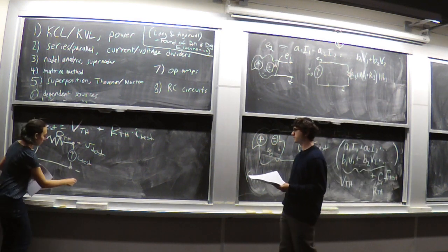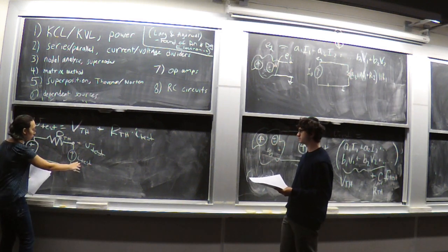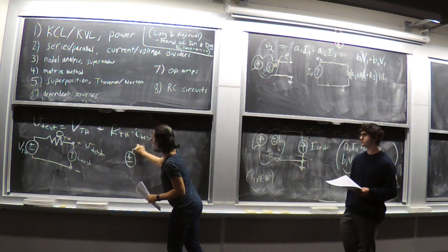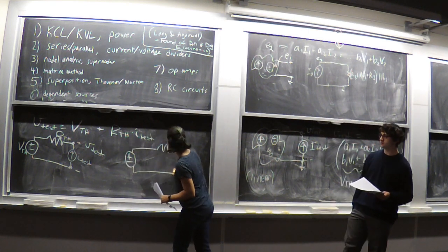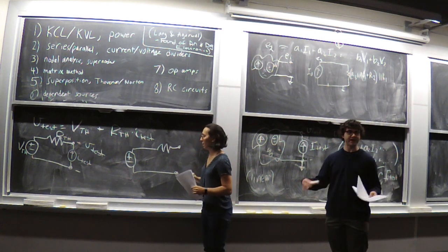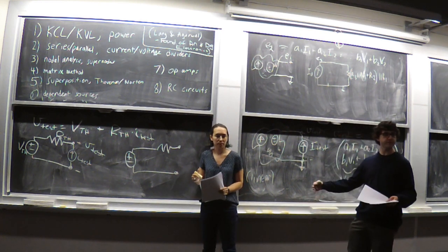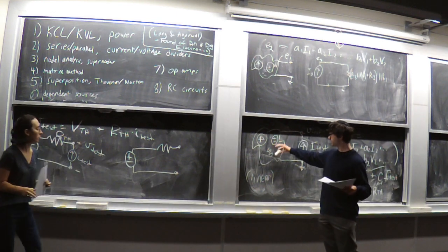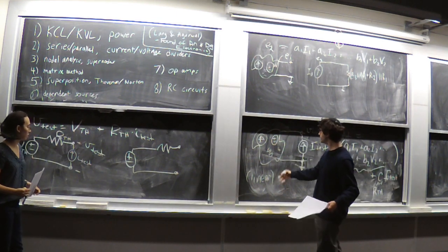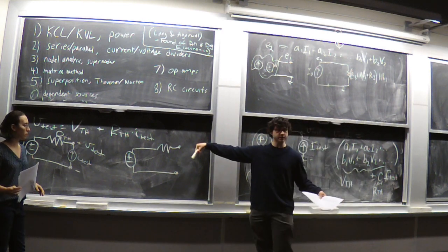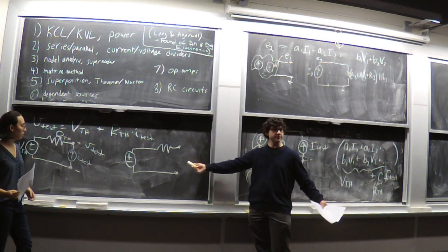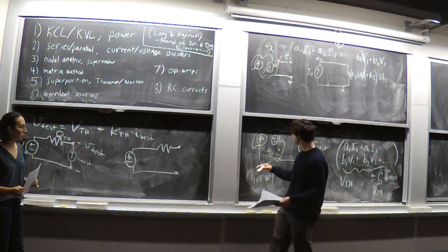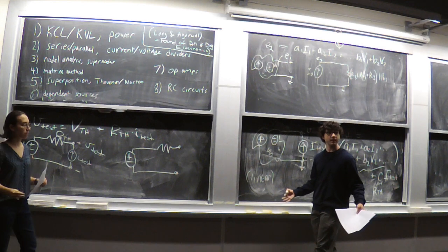And so ultimately, our Thevenin equivalent circuit, we don't include the I test, we just write it as this. Right, the I test was just a mechanism we were using to determine the values of V Thevenin and R Thevenin, but fundamentally the idea is that this entire mess of a circuit, whatever's in here, is equivalent, as far as we are concerned, to this, just a single voltage source in series with the resistor. And that can make your analysis a lot easier if you can simplify an enormous circuit like this.